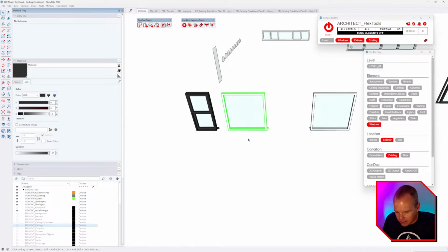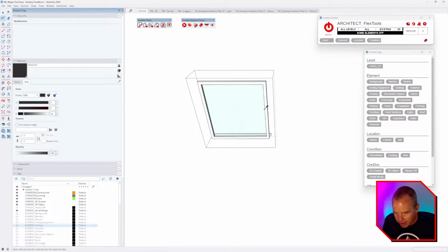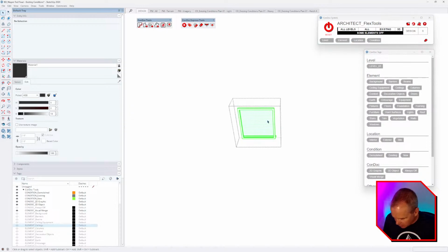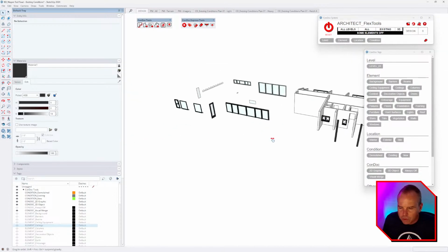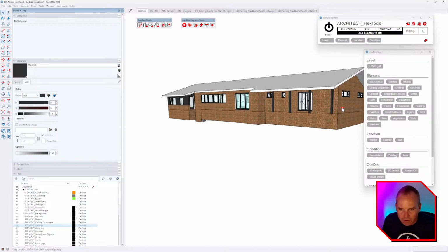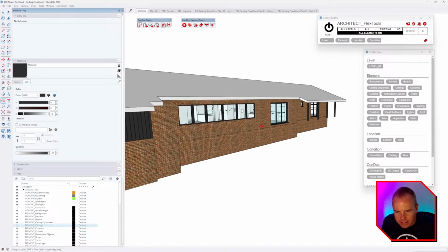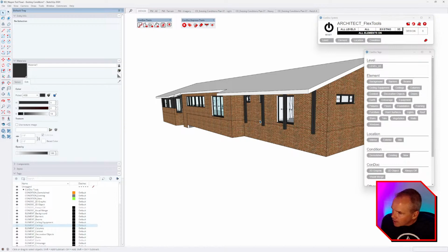It's essentially like a swap within this group. I can select this stuff, group it, double click in, explode everything, Control T, paint bucket tool, Shift, get those done like that. Select all, explode, Shift like that. So at least this way, if I were to make a rendering of this project, it's going to be looking at this area of the house, and so I just want this stuff to show up properly. That's all. It doesn't need to show up in the plans. As a matter of fact, I'm just going to really isolate this one area and not show anything else over there.